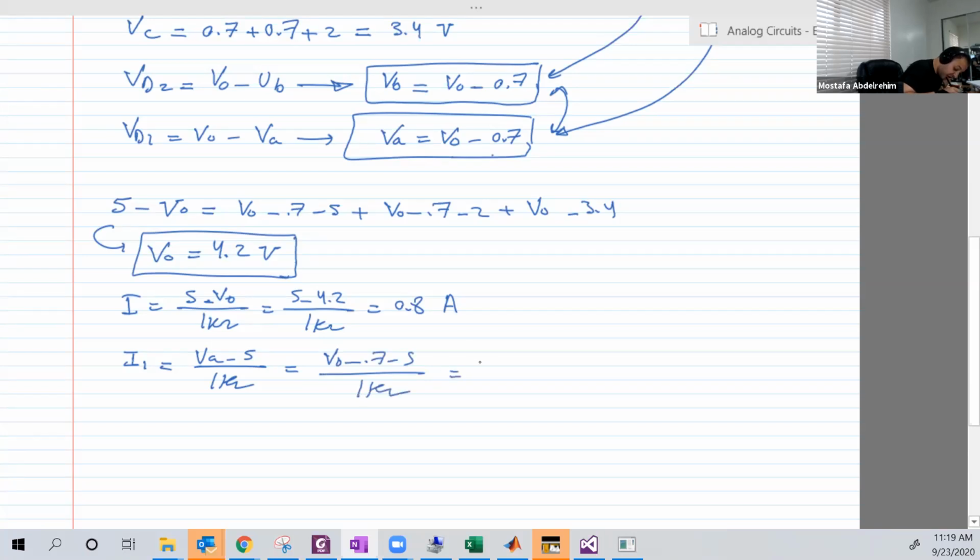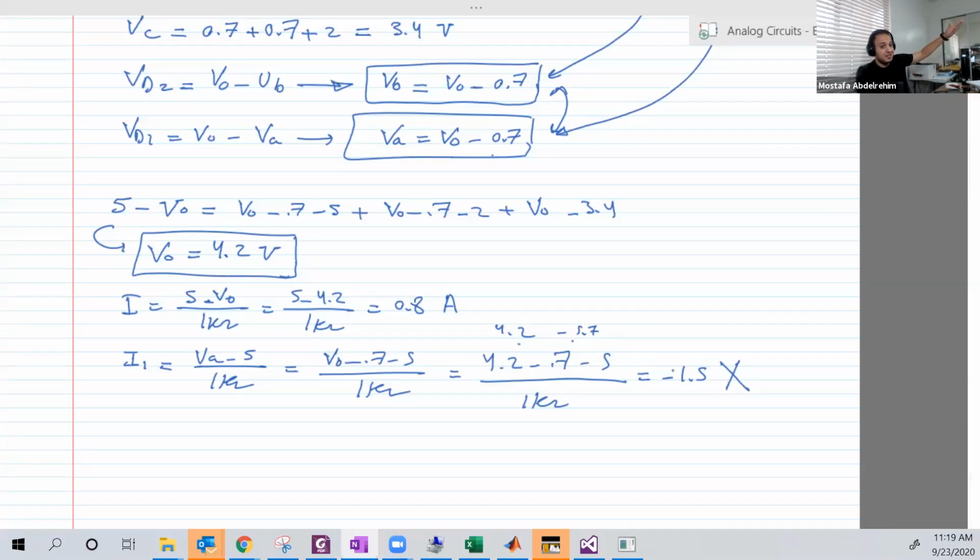But VO is known now, 4.2 minus 0.7 minus 5. What is all of that? So this is minus 5.7, 4.2. This guy minus this guy is actually minus 1.5. Is that correct? No, this does not conform to, or match, our assumption that D1 is on. But let's continue.